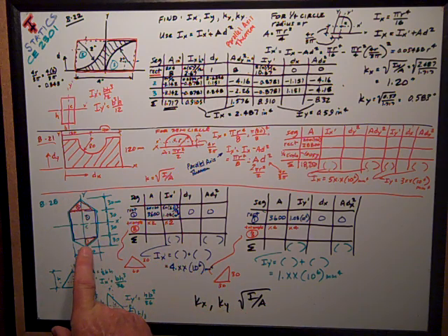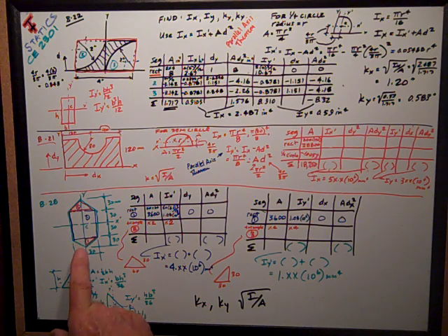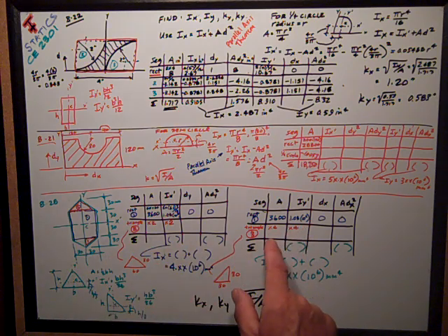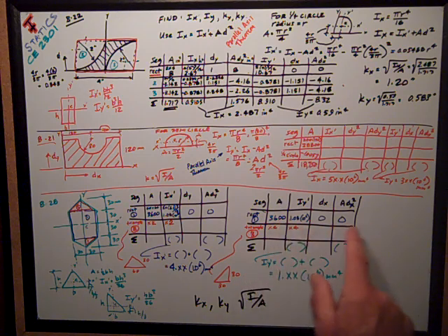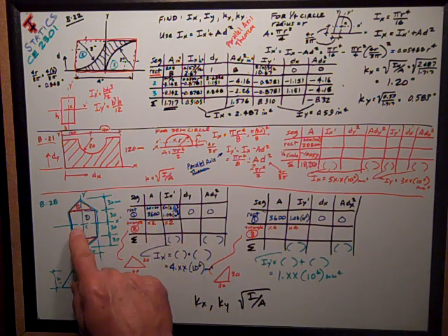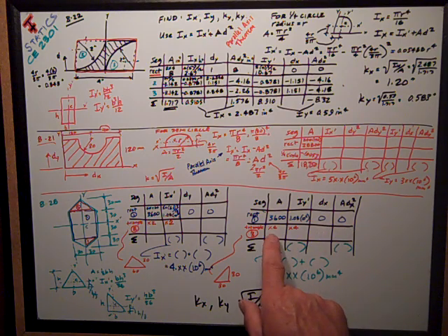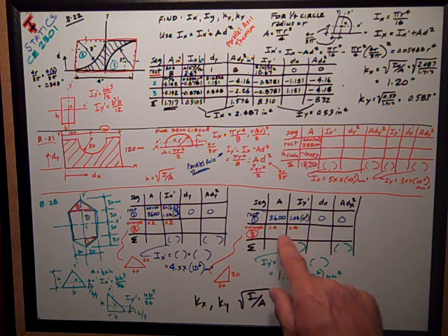I recommend breaking it up into 4 half triangles, 2 above and 2 below, shaped like this down here at 3. So the area of the rectangle is still the same, its moment of inertia is still the same. Its centroid is on the centroid of the overall area, so its dx distance is 0. For the triangle, which I've got 4 of, the area is a 30 by 30 triangle, so it's 1/2 30 by 30. Multiply that by 4 for this box.